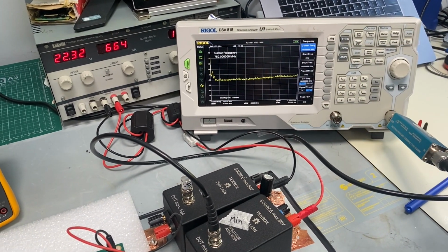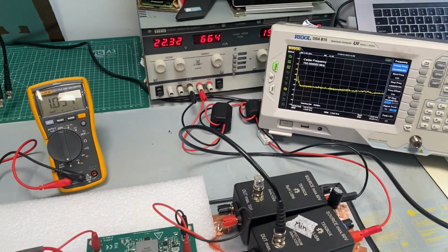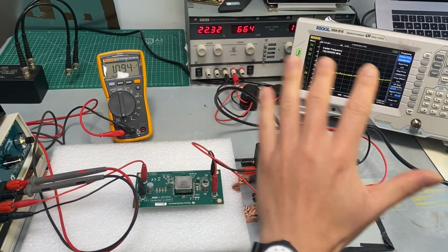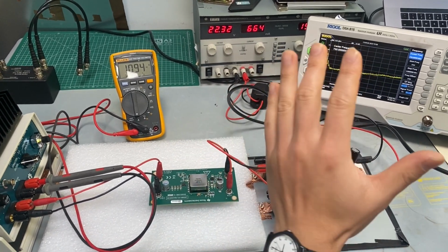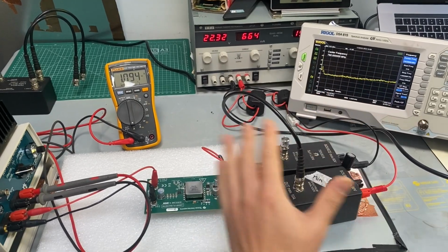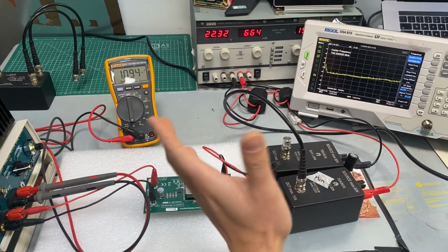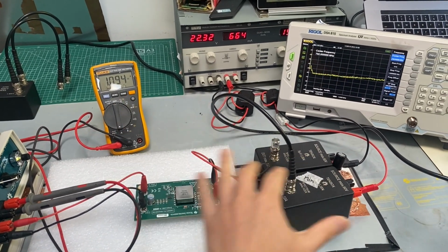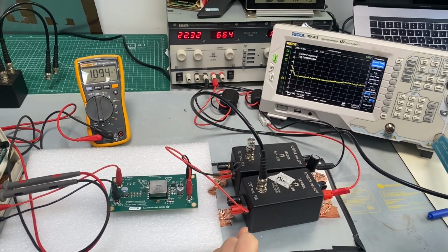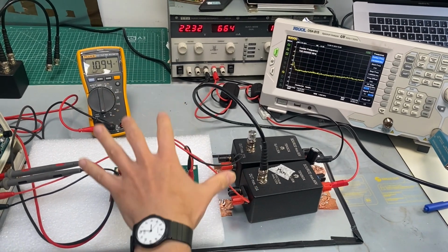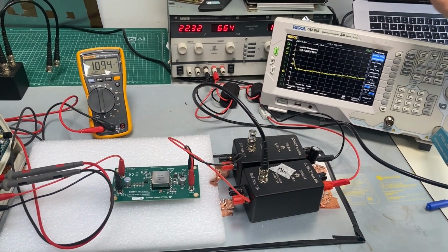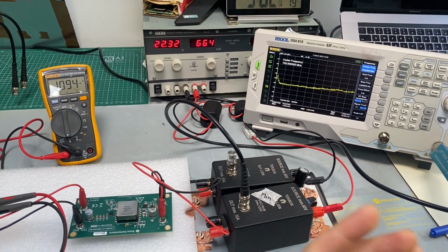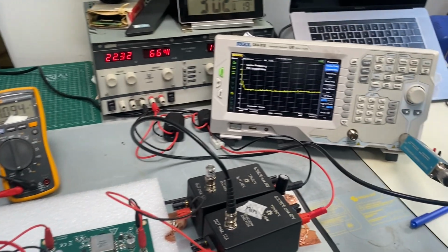Okay, now often for switching mode power supply, lots of the noise is predominantly in the lower frequency range. So we're talking about perhaps below 10 megahertz, or you sometimes have some high common mode currents in the 60, 70 megahertz, or perhaps 100 megahertz. But everything should be below 100 megahertz. So the reason I said that is because the first thing of using a spectral analyzer is you need to define the frequency that you're going to measure. So first step is always define frequency.